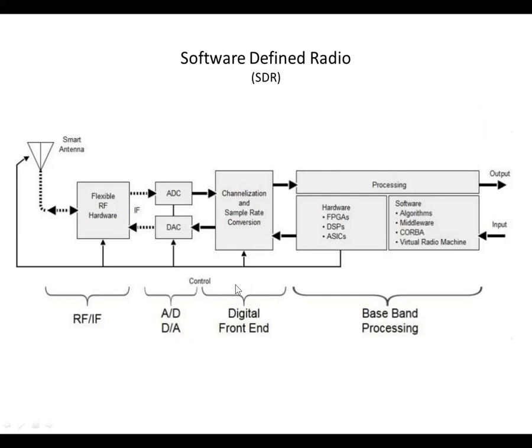Now, software-defined radio is another approach, where it has a much smarter antenna, I guess they call it. Essentially what you're doing is bringing the signal in, and you process the incoming RF signal to be ready to be converted from analog to digital. Then once you get the digital signal in, the computer inside does all the work in processing the signal, rather than active components like you have in a single sideband radio.